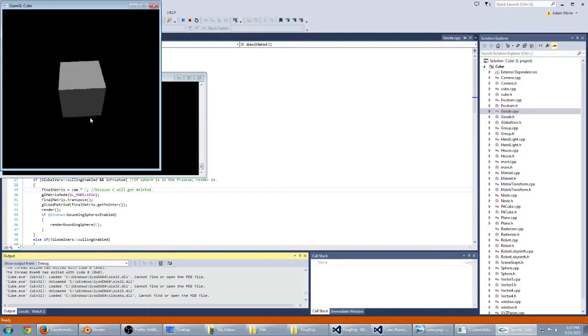You can scale it bigger, scale it smaller. You can say translate it by the y. I'm lowering the y's value of every vertex of the cube by doing that. I can move it by the x position, and I can also orbit it around the y-axis.